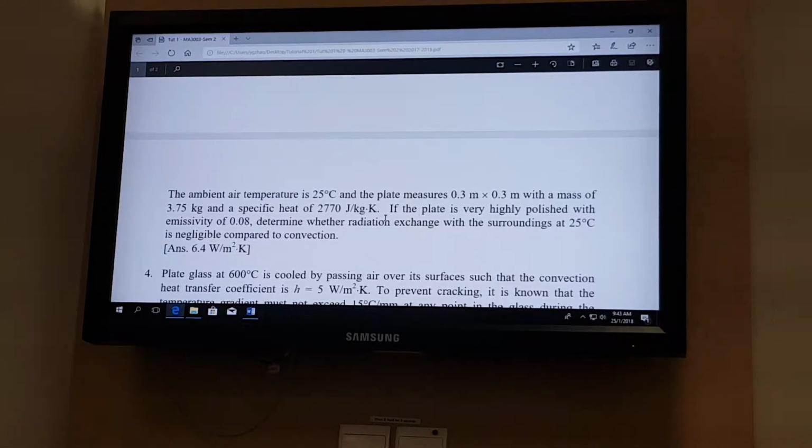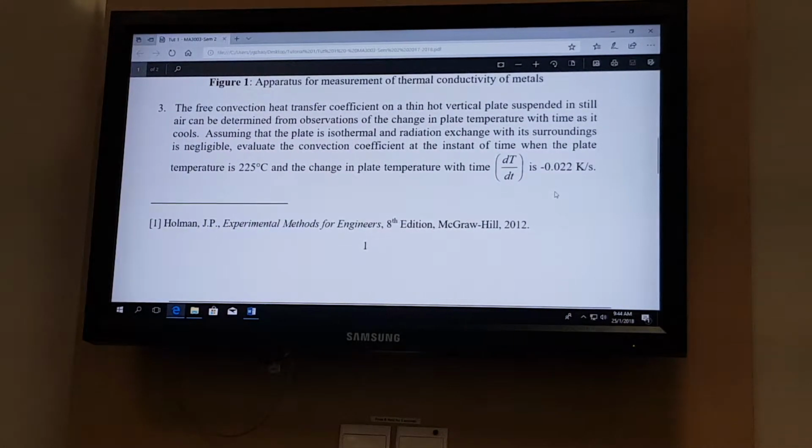Then, because it's a multiple process, we have to use this formula: E in minus E out goes to the system. So first we use convection: convection is 2 H A_s, where A_s is the area, times (T_s minus T infinity), equal to this one, as can be seen in the lecture notes.